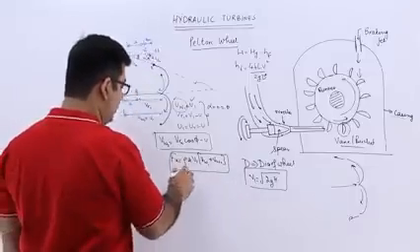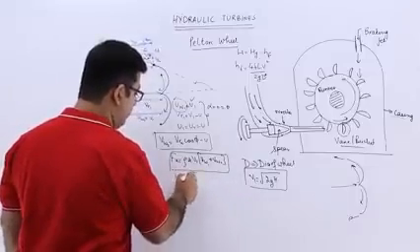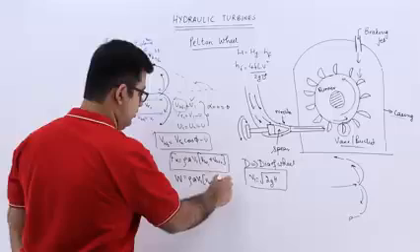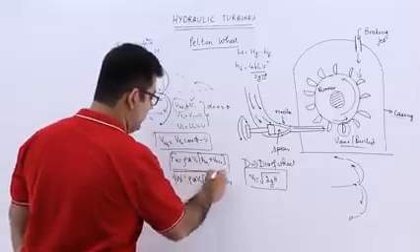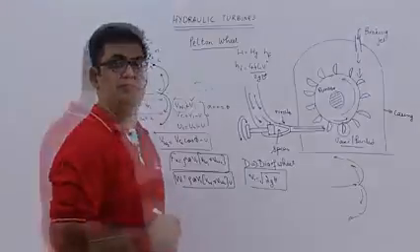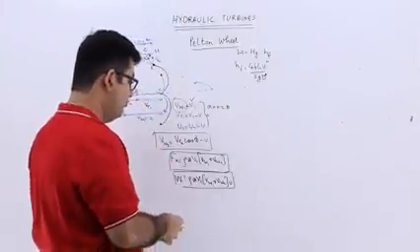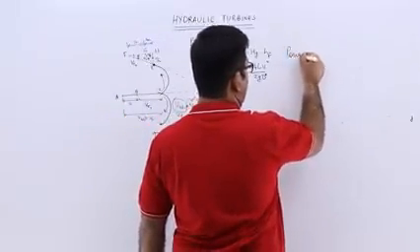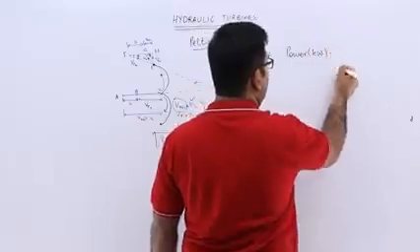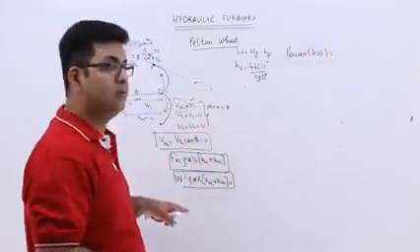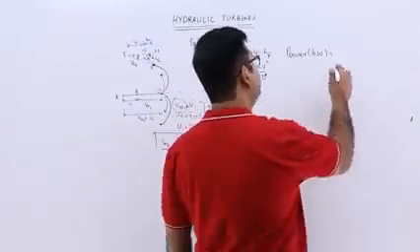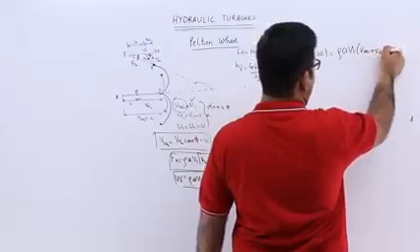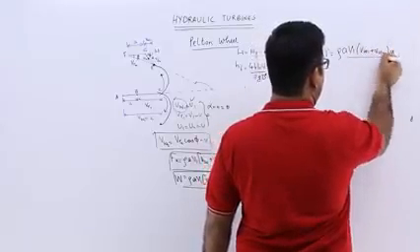Okay, so if you find out the work done per unit time, you will have rho A V1 into this plus this into U. So this is the work done per unit time. Then if you want to find out the power in kilowatts, this would be work done per second divided by 1000, because this is Newton meter per second. So you will have rho A V1 into VW1 plus VW2 into U divided by 1000 kilowatts.